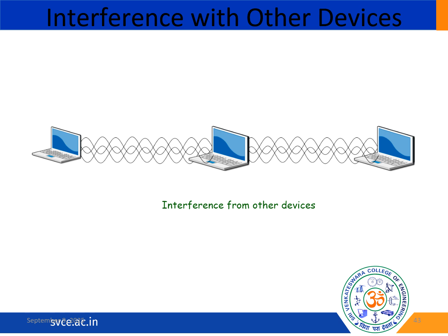For example, co-channel interference is one problem: multiple devices or networks use the same frequency channel, so they can clash, leading to signal degradation. Adjacent channel interference can also occur, where signals from nearby channels bleed into each other, causing overlapping and confusion.